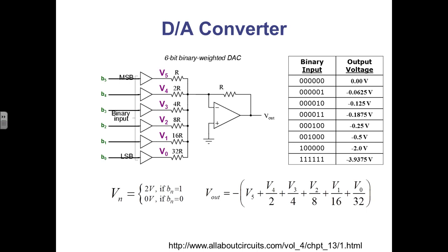In terms of architecture, what's inside of a D to A converter? Here's this pretty standard kind of drawing. You can think of a D to A converter as a bit of a summing amplifier where my binary bits come in on the left and they go into a weighted resistor ladder network, where each bit provides a different proportional amount of voltage through this amplifier on the output. So the most significant bit would create a larger voltage, twice as big as the next bit below it, using this configuration.